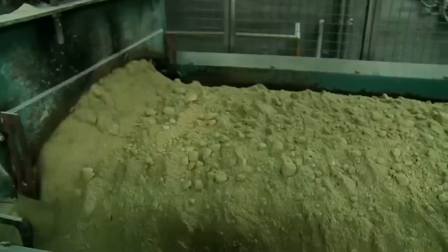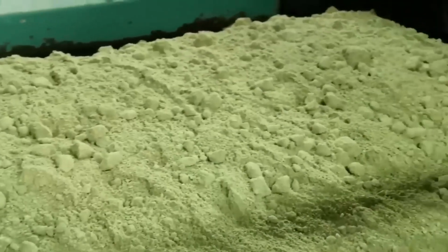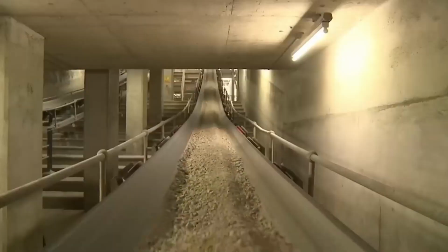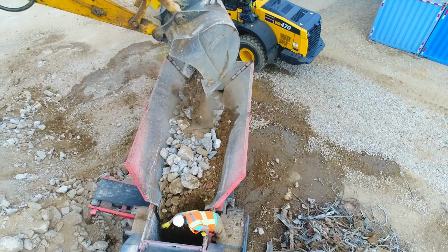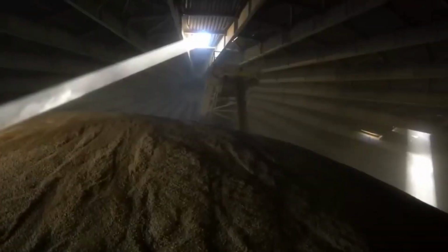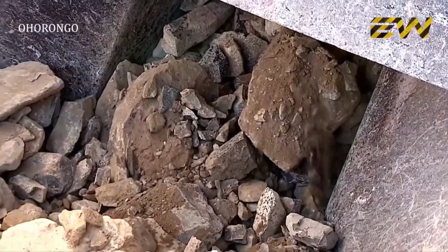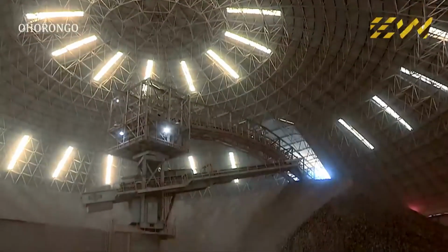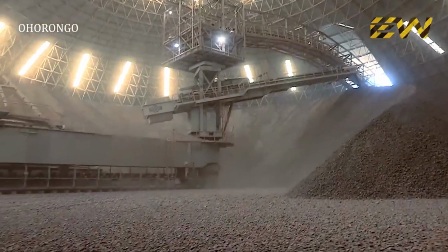At the crushing plant, the rocky chunks of quarried limestone and clay are fed through a series of crushers to break them down into smaller fragments. The crushing process typically involves a primary crusher, secondary crusher, and even tertiary crusher to achieve the desired size reduction. The crushed materials exit the final crusher onto conveyor belts that carry them to the raw mill storage domes.